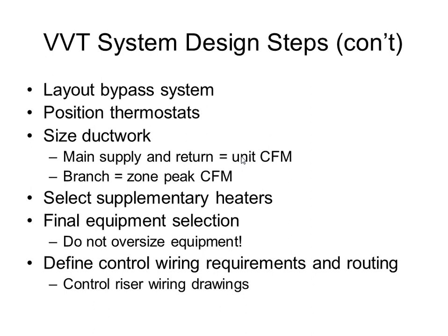And then finally, you'd want to go into selecting what specific equipment you need. You would talk to your manufacturer, your rep, and say, hey, I need a 15-ton rooftop unit and 6 zones. And then if you talk to Carrier, we'd give you a 48 TC, something along those lines. And then you would go into your control system for the VVT and what type of wiring you need, all of that.